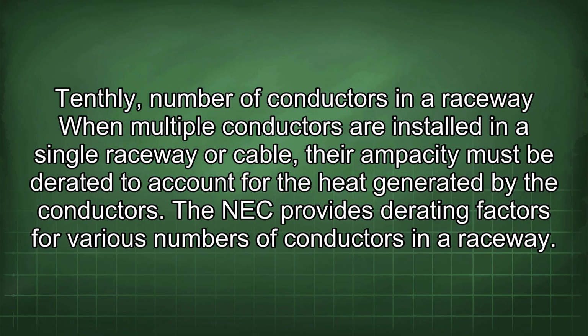Tenthly, number of conductors in a raceway. When multiple conductors are installed in a single raceway or cable, their ampacity must be derated to account for the heat generated by the conductors. The NEC provides derating factors for various numbers of conductors in a raceway.